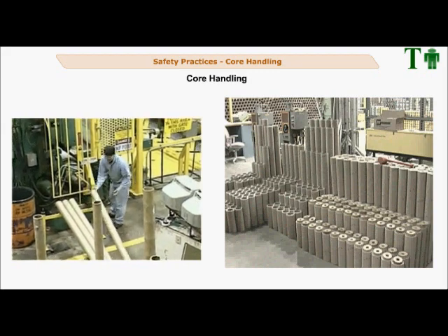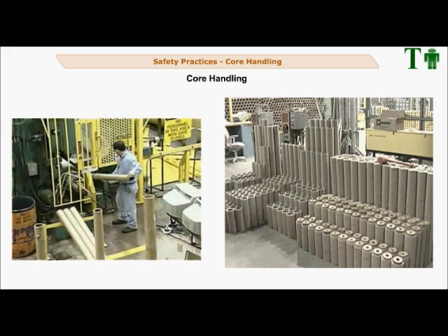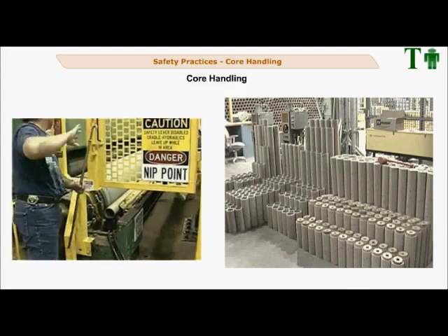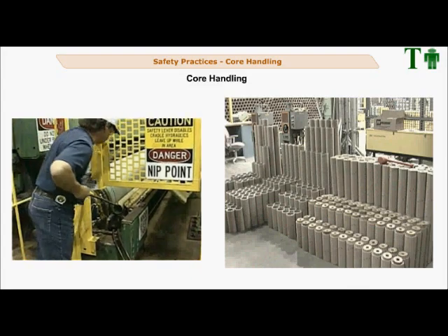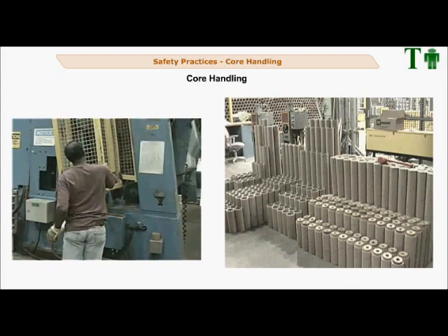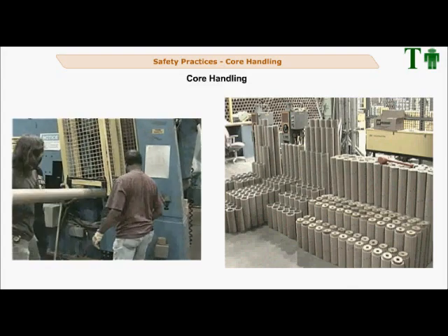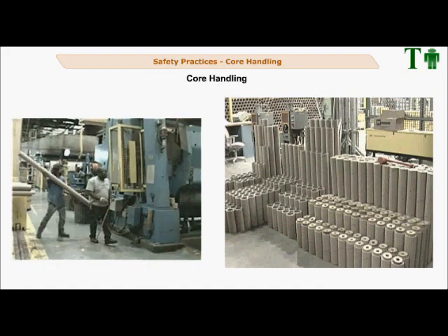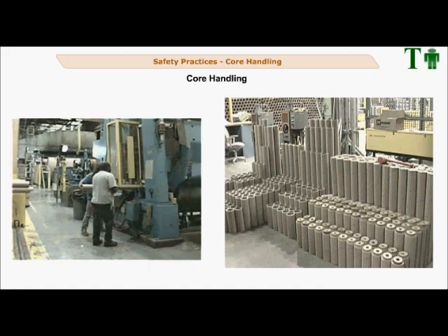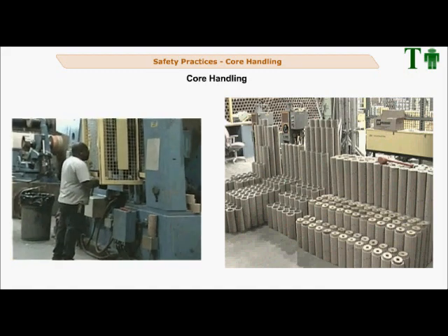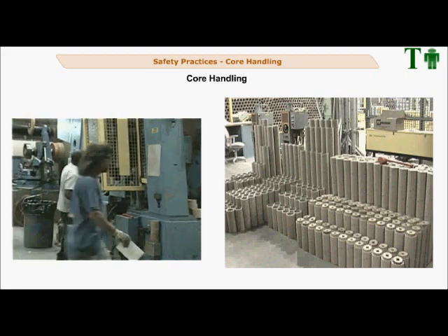Other hazards are twisting your knees and back, repetitive motion, standing long periods on concrete surfaces, wrist fatigue, and injuries from gripping and handling. Soft tissue injuries have occurred in the past due to the repetitiveness of this process. Be careful handling cores. To help eliminate injuries taking place while handling cores, the following tools should be considered: ergonomic studies, job rotation, safety mats, etc.